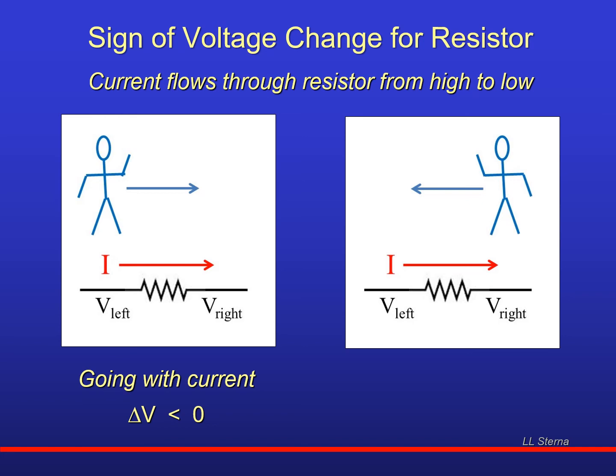So if you happen to be looking at a circuit like it, you might say, well, I'll always go from left to right. That's not an option. If you're going around a loop, go across the top, the bottom, you're kind of circling around. You're not always going from left to right. So on the right-hand side, you're walking from right to left. But the current's going from left to right. You're going against the current.